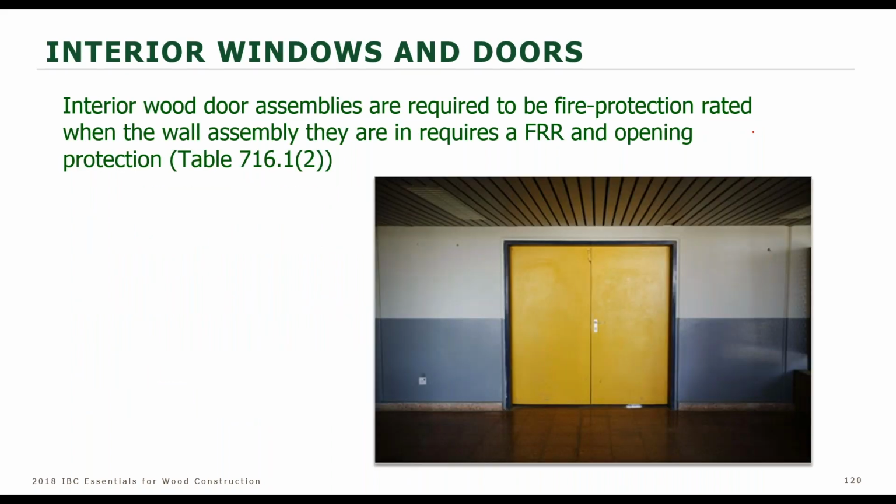The interior doors can always be wood. Even wood doors can have a fire protection rating, of course. If the door is in a wall that's required to be fire resistance rated, it does have to have a fire protection rating, has to be a listed assembly. So be careful with that.